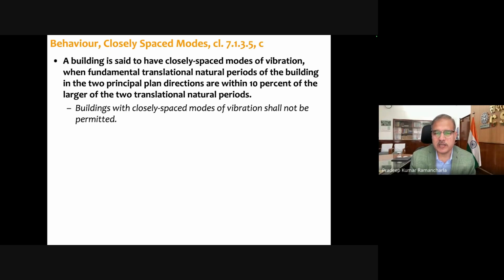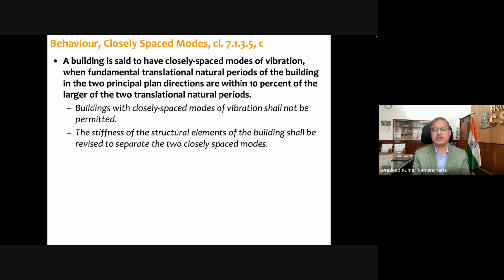Then closely spaced modes. So when do we call this closely spaced modes? If the difference between the first mode and the second mode, or any two modes, falls within 10% of the higher mode in the two principal plan directions, then we call it closely spaced modes.